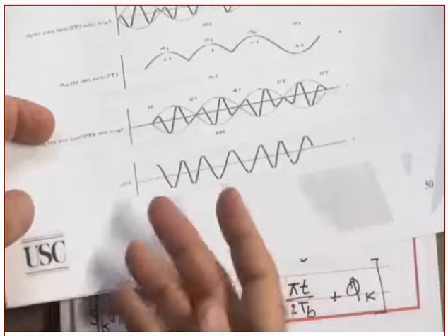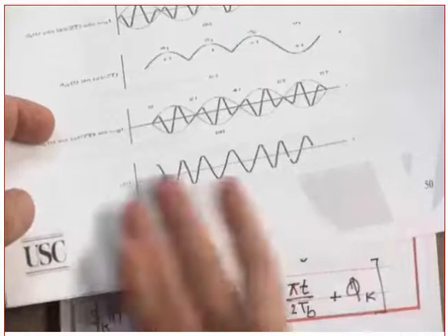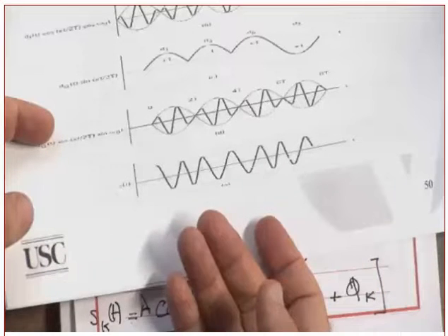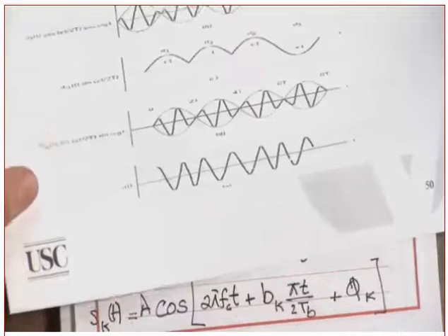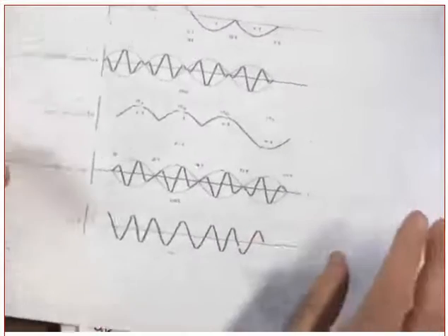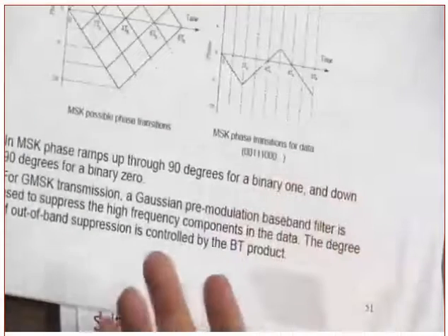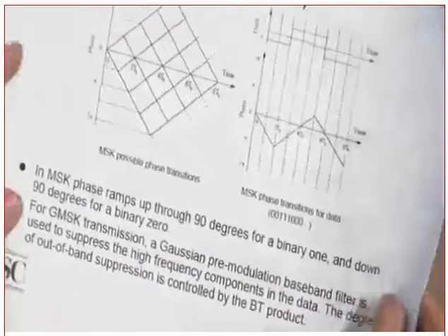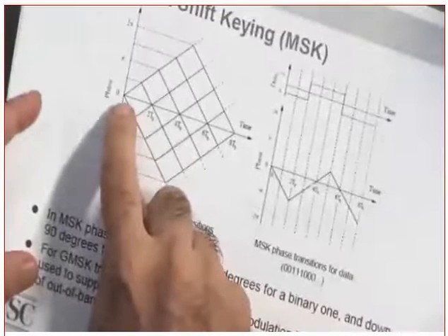Constant envelope all the time. Why? Because the amplitude is fixed. Did you get my point? Yes, there is no sudden change between the phases. So they allow them to use the power amplifier at its highest efficiency level. They don't worry about non-linearity, because the amplitude is fixed. Clear?